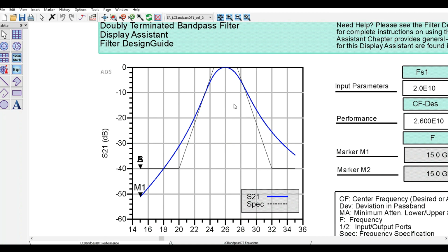this base design, we need to try to optimize it or change parameters again because it does not meet our design specification. Because we gave that 20 gigahertz, we should have at least 40, but here we're having about 30, 32, but it's not up to 40 our design. On this side too is the same thing. So at 32 it's giving us about 26 dB, which means this particular design does not meet our design specification.